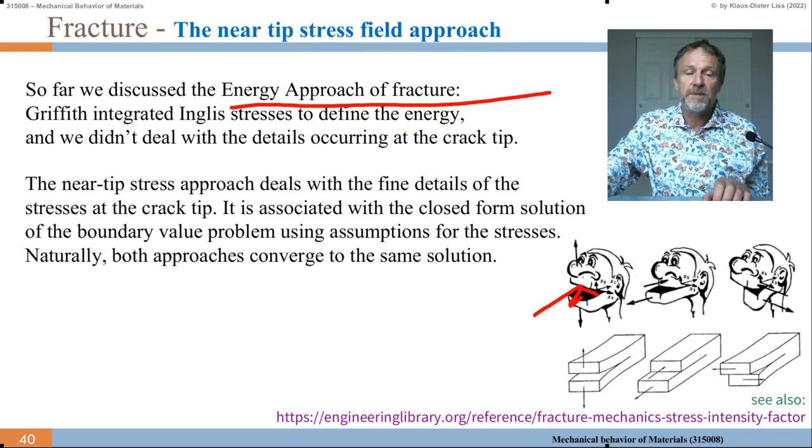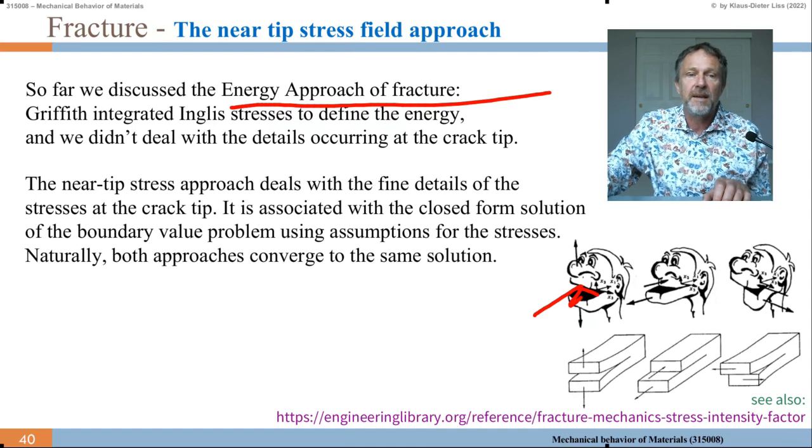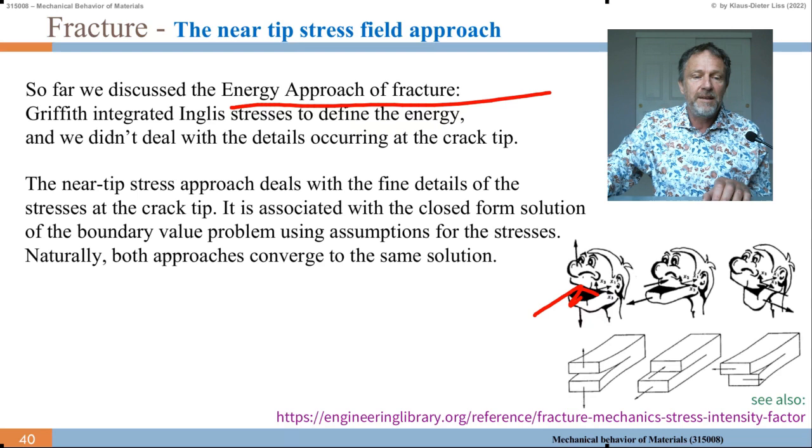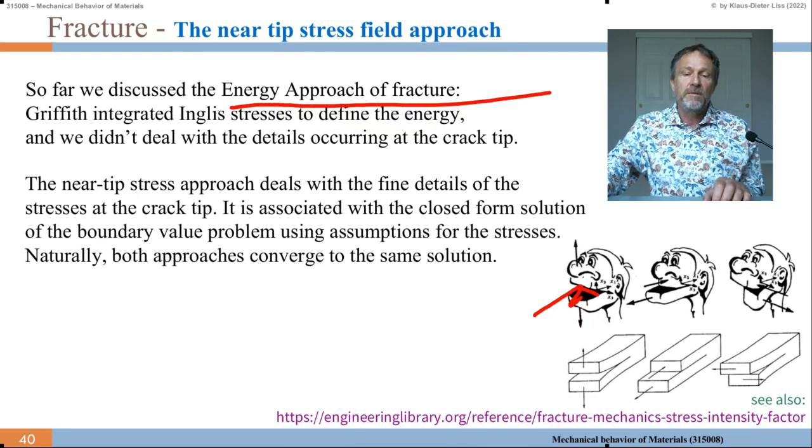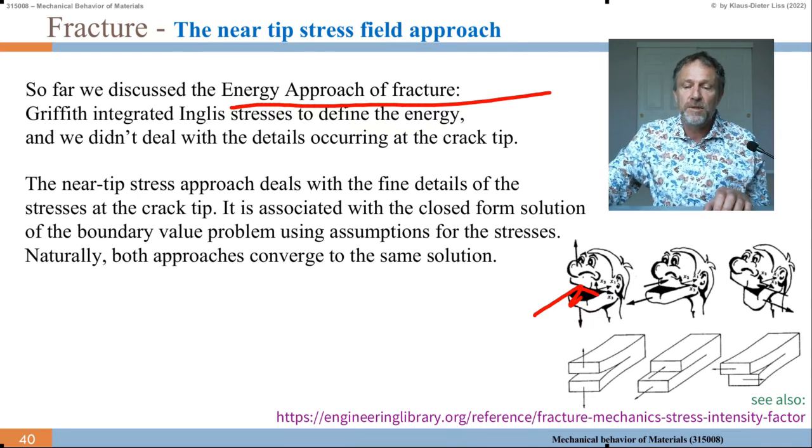The near-tip stress approach deals with the fine details of the stresses at the crack tip. It is associated with the closed form solution of the boundary value problem in plane stress and plane strain theories, and naturally both approaches converge to the same solution.